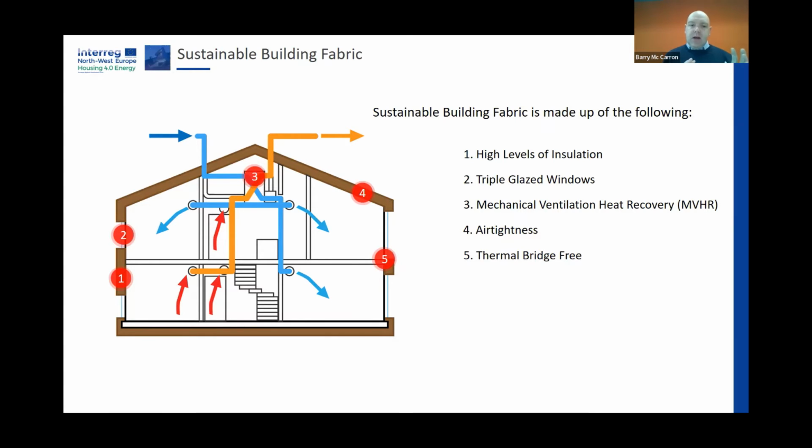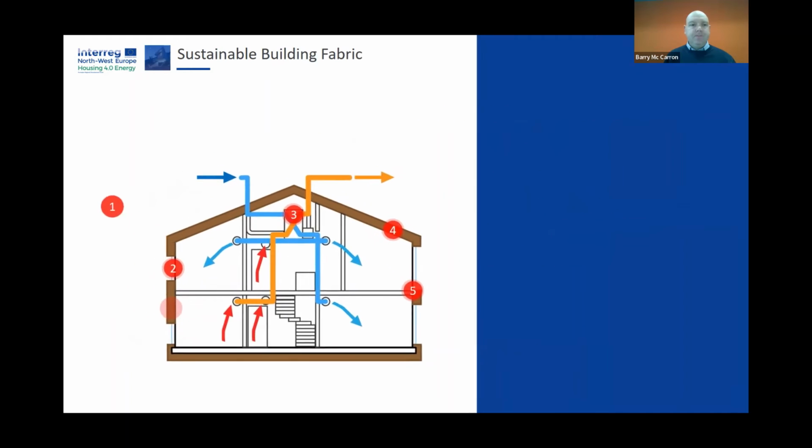So the air tightness and the mechanical ventilation go hand in hand. That's the key. If you have a particularly airtight building and you are not going mechanically ventilated, that's a recipe for trouble. Or equally, if you're putting in a mechanical ventilation unit and the building is not particularly airtight, you're going to get trouble. And another area of trouble sometimes is also around this thermal bridging issue. So again, I spent a bit of time on that slide, but I think it's a very important one, and I look forward to discussion on that later on.